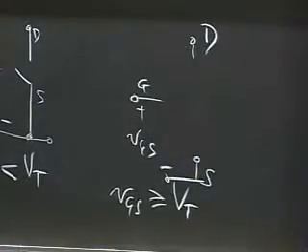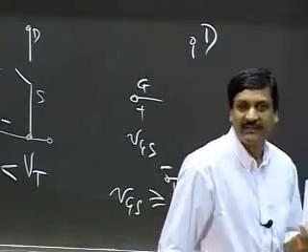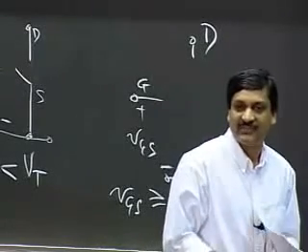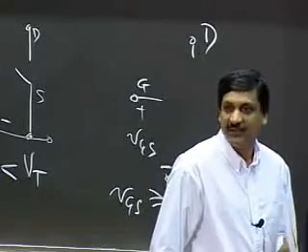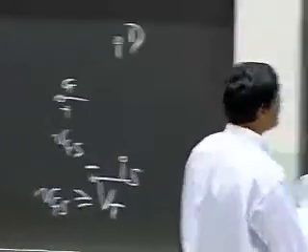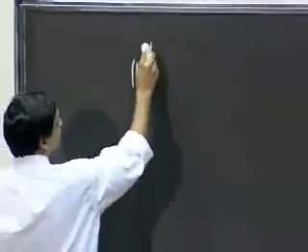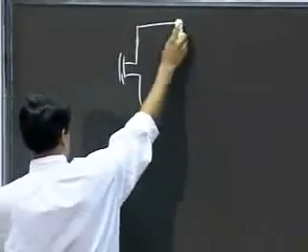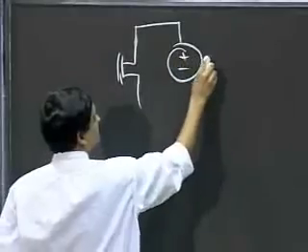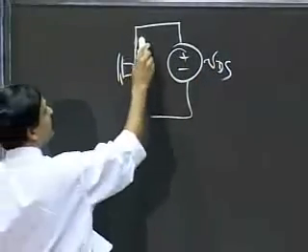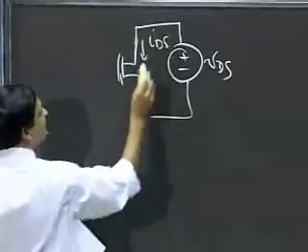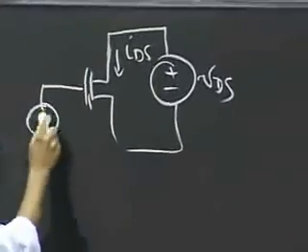So what I'll do next is put the MOSFET, apply some voltages on it, and observe the current versus VDS behavior, and plot that on a scope and take a look at it. Figure out what IDS looks like.